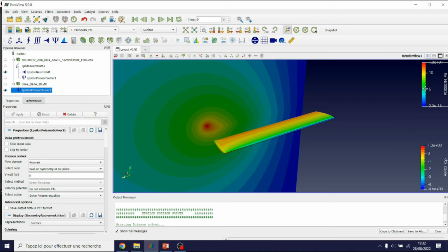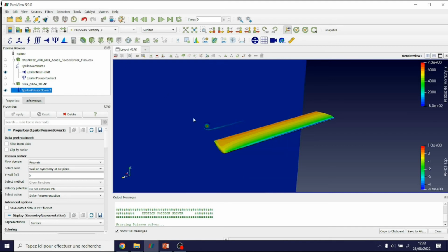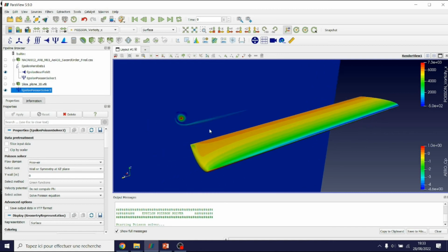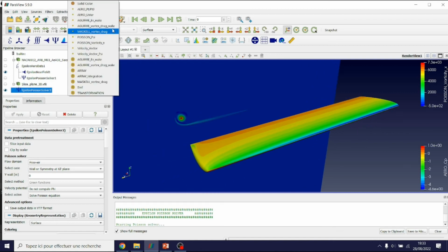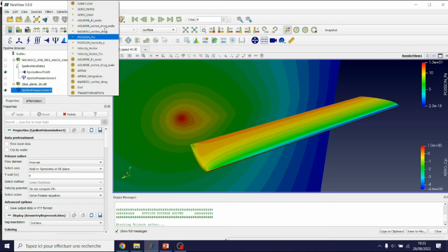What really matters is the product of the stream function and the vorticity, which must be locally positive, because that gives you the vortex drag. In fact, you have here in Poisson two options: psi is the stream function itself, and also you have the actual vorticity, xi. And again, it is the product of both fields, the vorticity and the stream function, that gives you locally at each point the density of vortex drag according to the Maskell method or the weight-reduced vortex drag calculation.